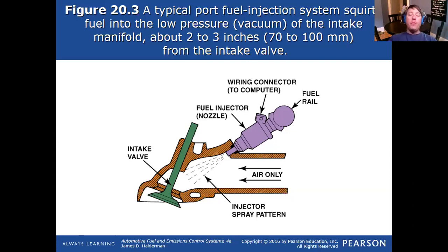and cool up. Because that was another issue with central fuel injection and carburation. We're just spraying fuel on the top side of the intake manifold, and that entire air charge has fuel in it, but it doesn't have equal fuel distribution. It doesn't have equal atomization of fuel. It doesn't have equal air-fuel ratio. It's close enough to where the engine can run, but it's not good enough for efficiency factors.